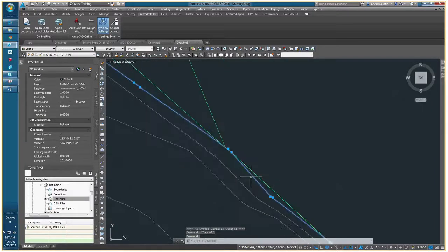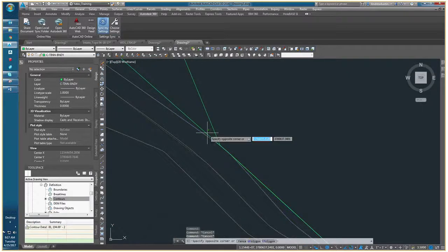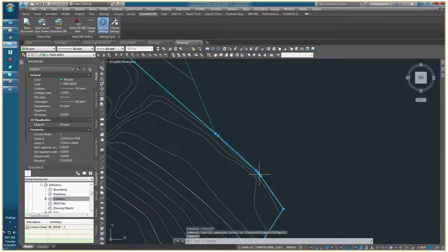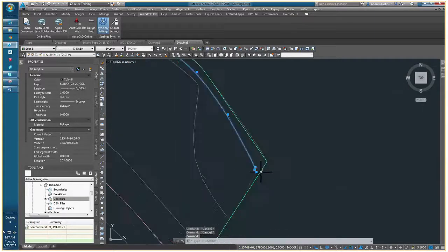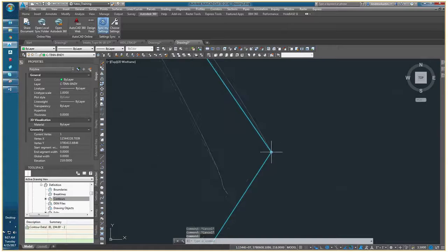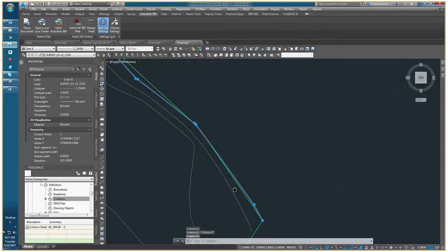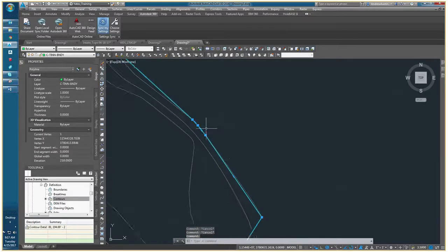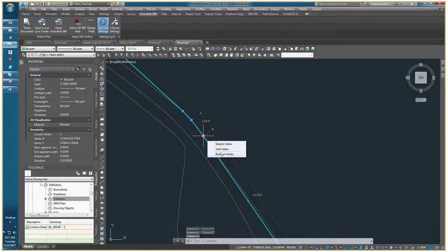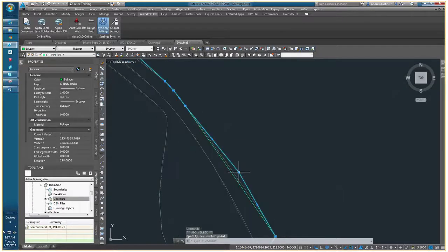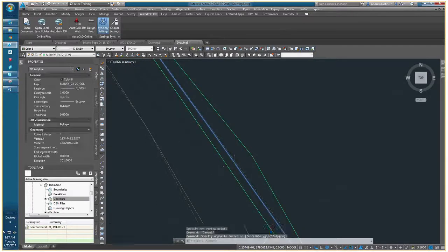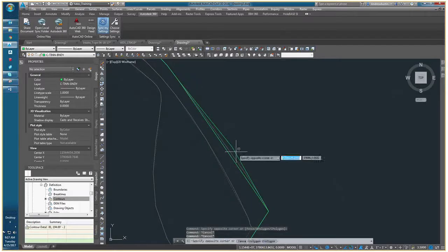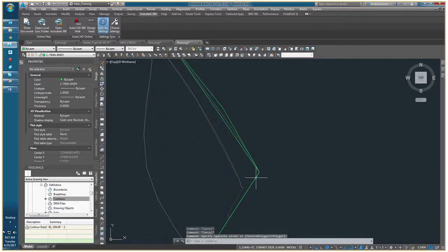As we get over to the edge here, we can see that the boundary is doing what it's supposed to for the most part. Over here, not quite. We're missing a piece of data here. So we are going to need to expand instead of contract this surface boundary out a bit, just beyond that piece of contour data. And then we'll keep going around the surface.